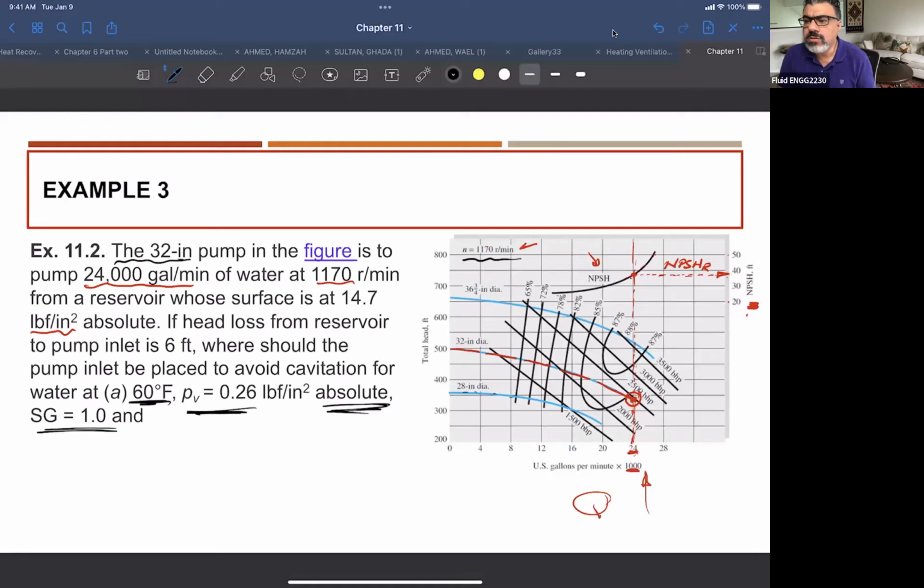A well would use a positive displacement. No, not again. I'm not saying this has to be, but you have seen many times there is something called a plunger pump. It's similar to the positive pump. The general idea here is to make sure that cavitation does not happen, or that the pump can start by itself, right? So in this case, I agree with you that we can use a different type of pump.